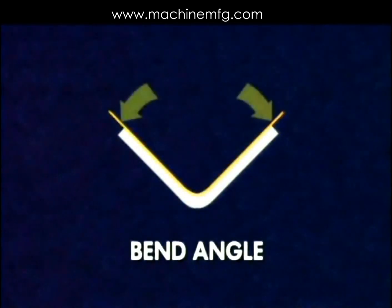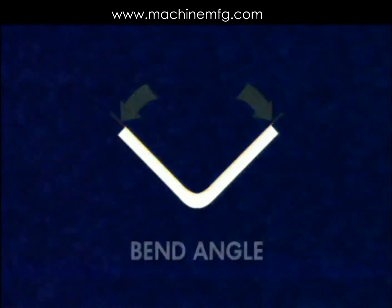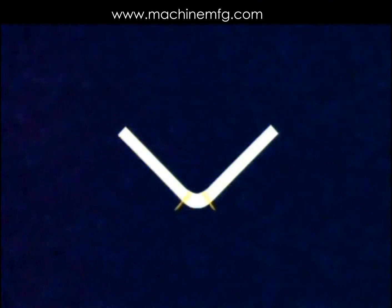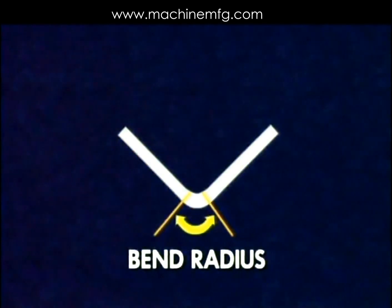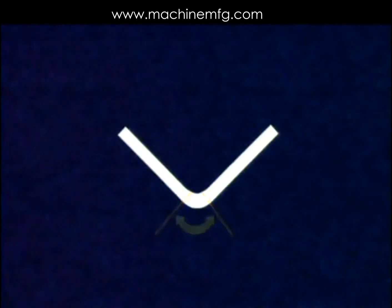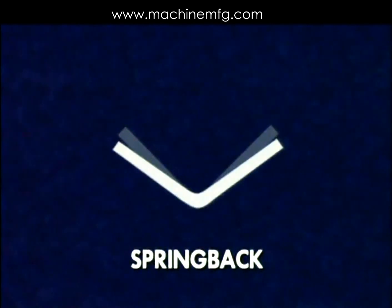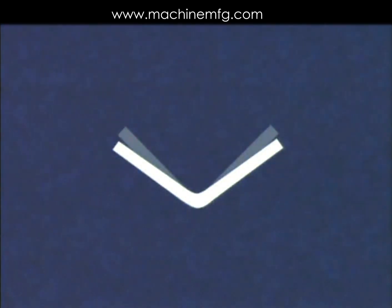The bend angle is usually the included angle of the bent workpiece. It can also refer to the supplementary angle formed by the two bent tangent lines. The bend radius is a tangent line where the flat, straight section of the part stops and the radius of the bend begins. Springback is the tendency of the material to return to its original form. Springback typically ranges from 2 to 4 degrees.